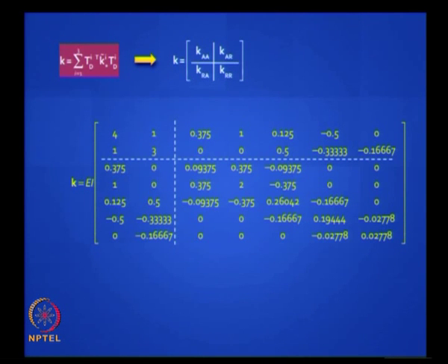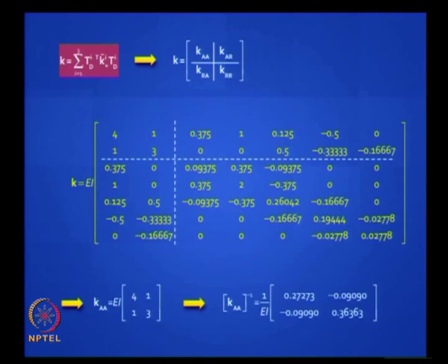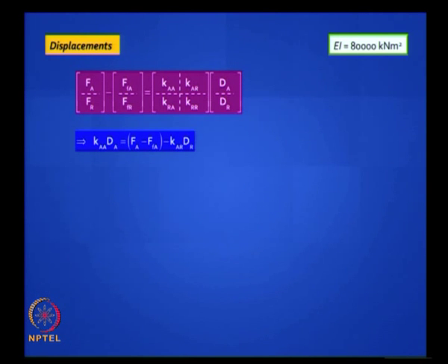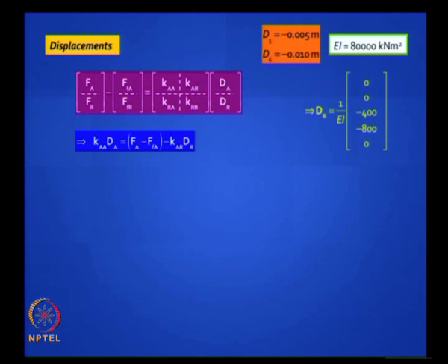You don't worry about the size of the whole matrix. It's 7 by 7, it looks scary. But we want to only invert 2 by 2, that's Ka, you can pick it out, and inverting it is easy, and you are ready to take any load. But the loads are also known, these equations are well known. It is always good to find out Ka, dA directly.